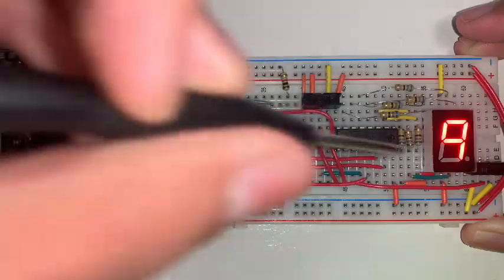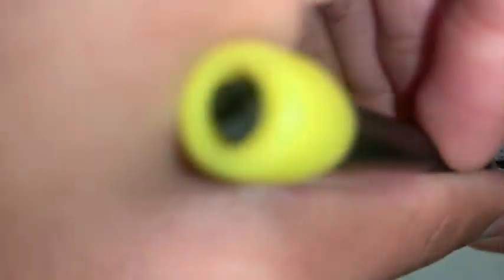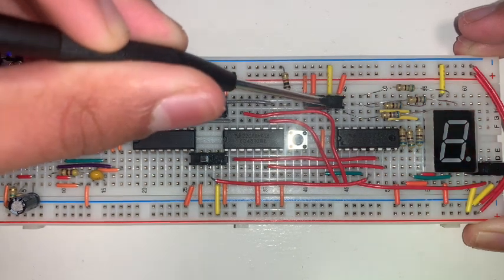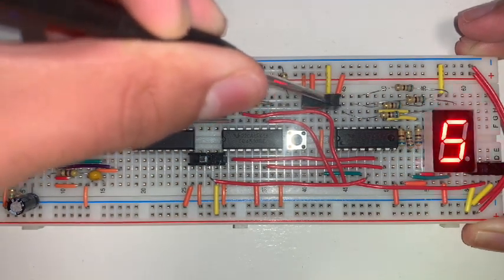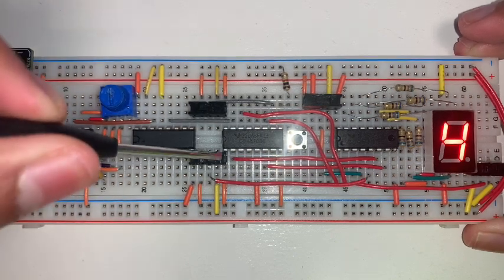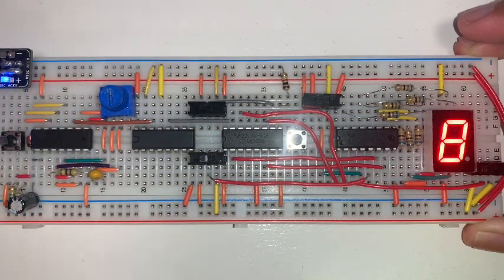3 new features are added. Firstly, the display test, which, toggling high, turns on all segments, showing 8. Secondly, the blank input, which, toggling high, turns off the display. Thirdly, the store, which, toggling low, stores the number internally. For all 3, the circuit continues counting internally.